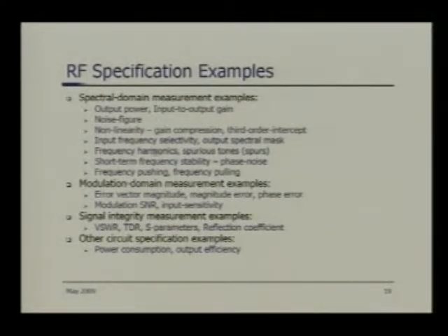Next one is frequency harmonics. Probably this is the one we encounter first as we study electronics. Every frequency that comes out of the RF output of some RF block will go through nonlinearity. So there will be odd harmonics as well as even harmonics.